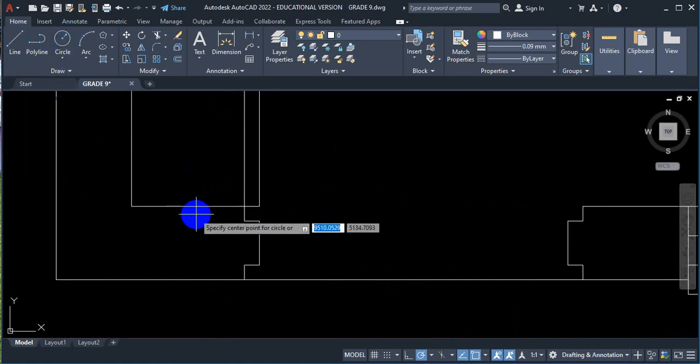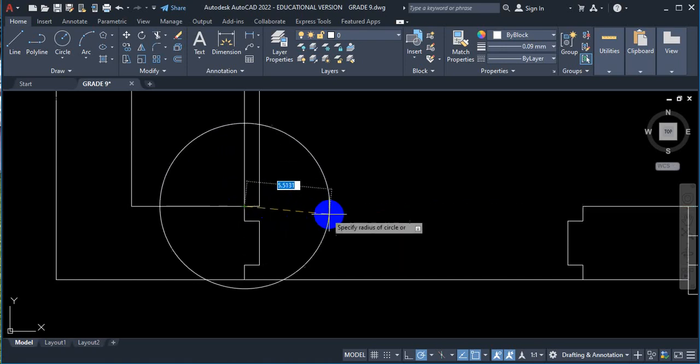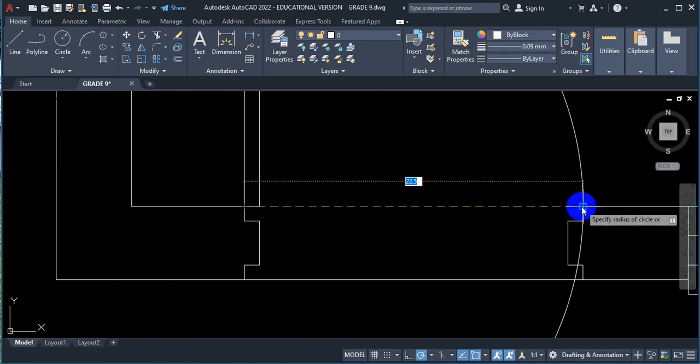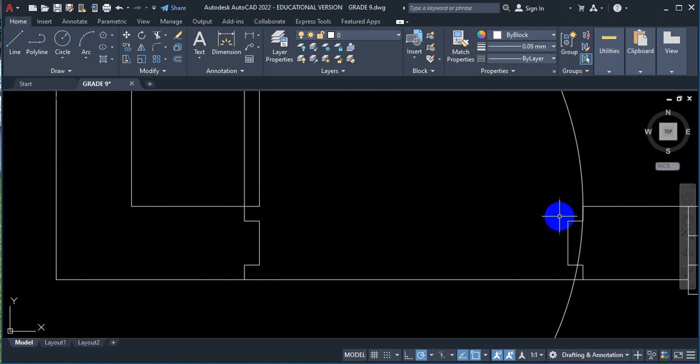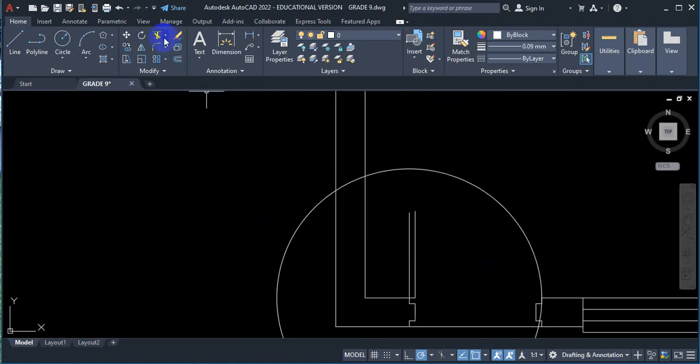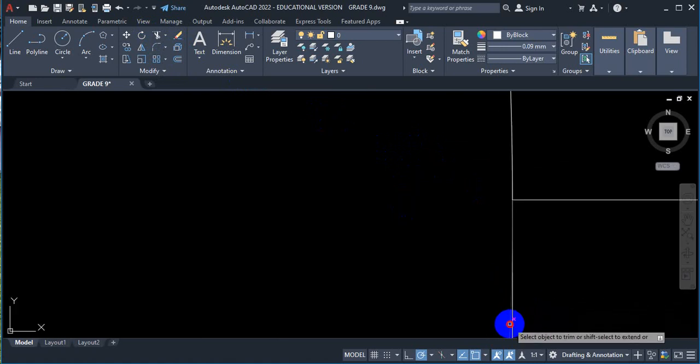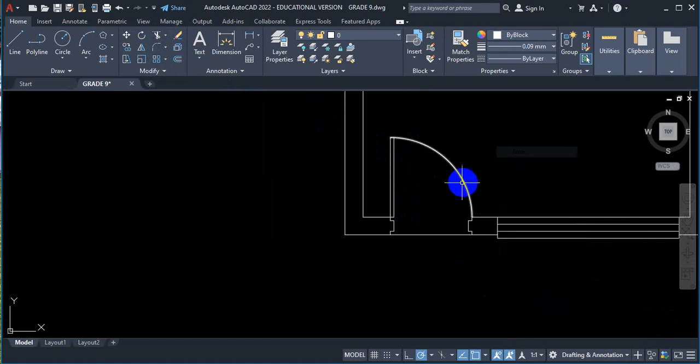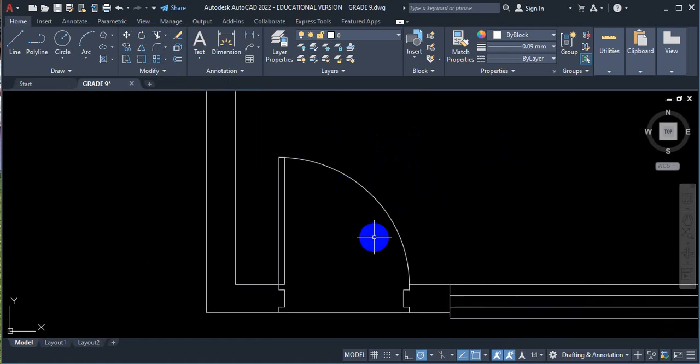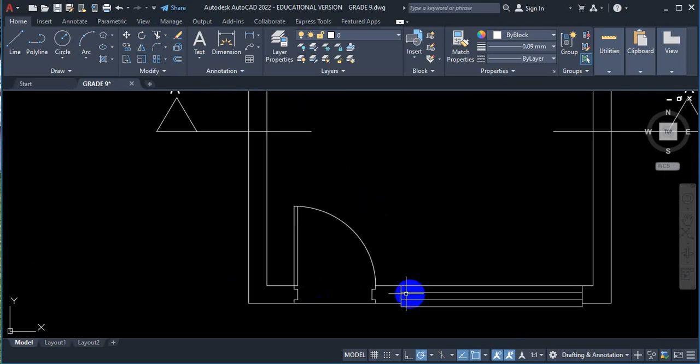Now we need to get our compass, place it at this point, open it to that position, because that's where the door will get into, open to that position, and it means our lines were short, so it means now the lines need to go and touch the circle. Now that's your door. So the door swing is this here. That's your door swing. So it's going to swing until it gets in there. So this is how then we get to draw the door. So that is your door, swinging towards the shortest wall of this building.